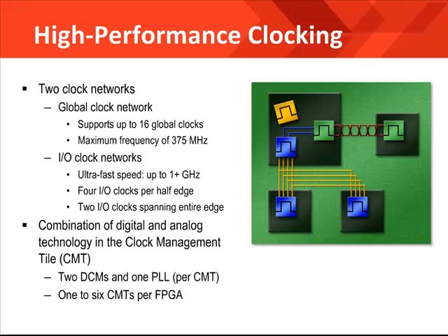device. Spartan-6 also includes 2 DCMs that are commonly called digital clock managers, and 1 PLL or phase lock loop per clock management tile, which is commonly known as a CMT. The CMTs are a combination of analog and digital technology.